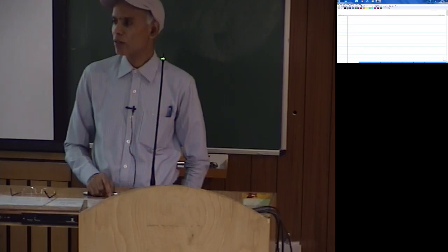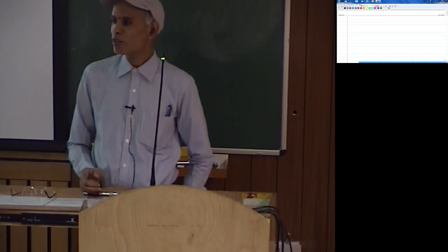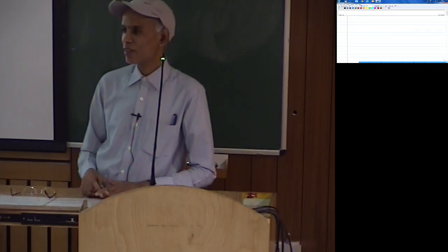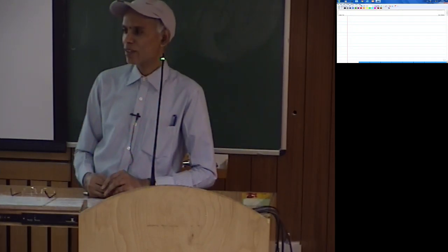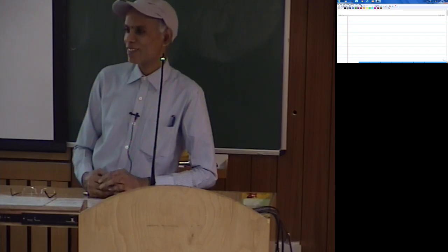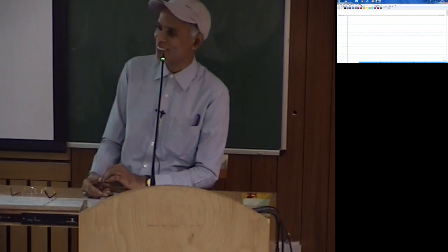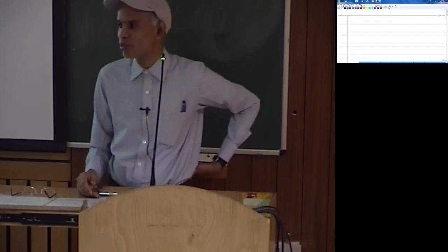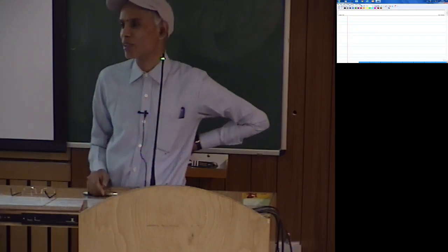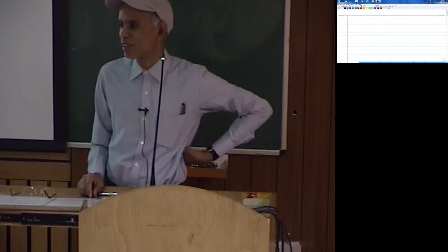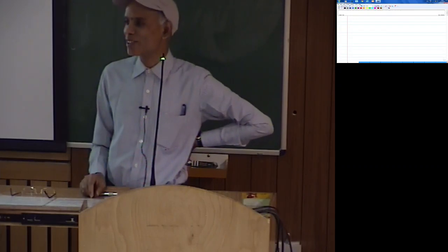So what about 1D? You can use natural coordinates there as well. Actually, we are telling to use this isoparametric element in 1D also. In really 1D you can't call it isoparametric, but you can use natural coordinates. You can express the x coordinate, or basically the independent coordinate, in terms of the natural coordinate and also the field variables. So the approach is similar.